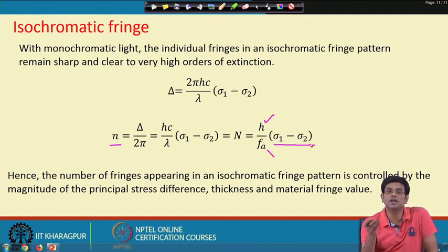So in such cases, we coat a layer of birefringent material on that body, and then we do the photoelastic experiment. When the body is stressed, the coating is also stressed. So the stress we get from that birefringent coating is the surface strain.